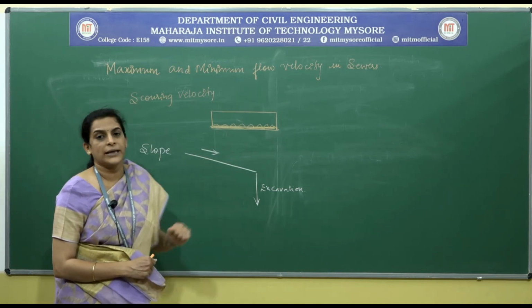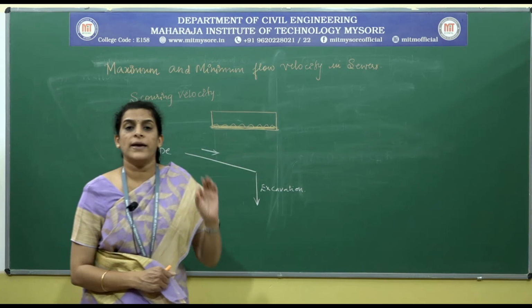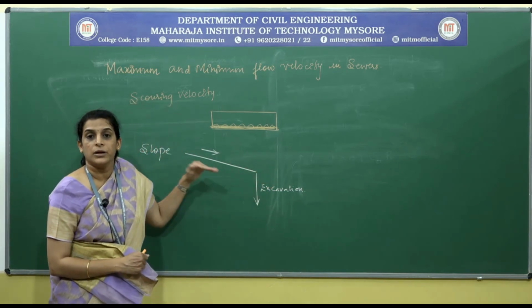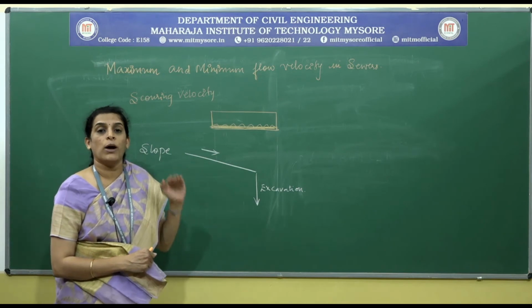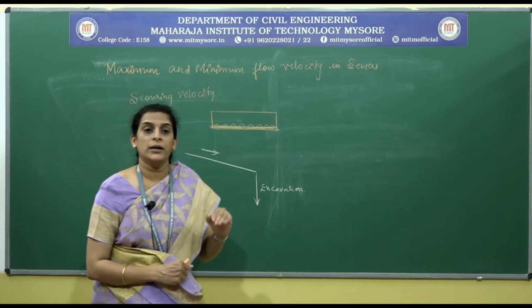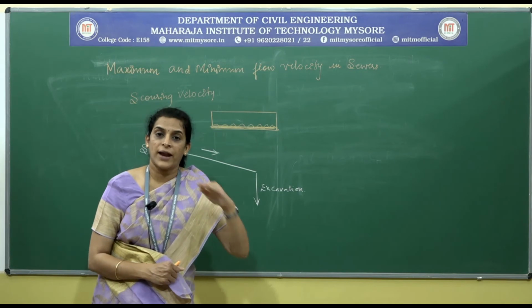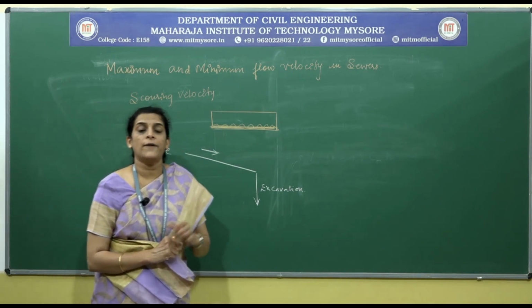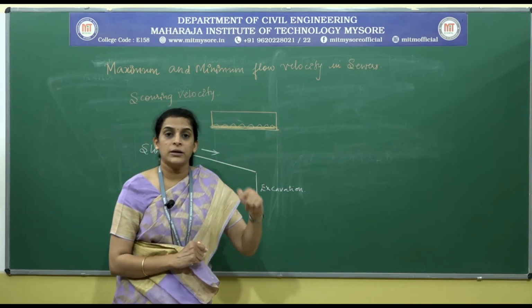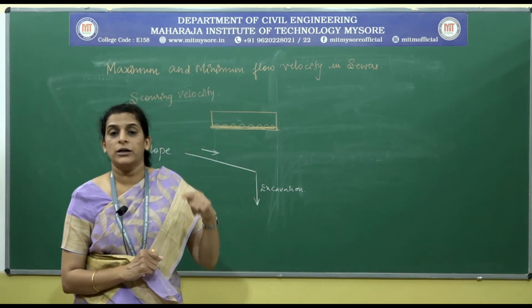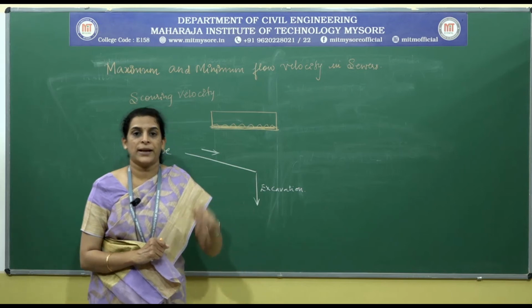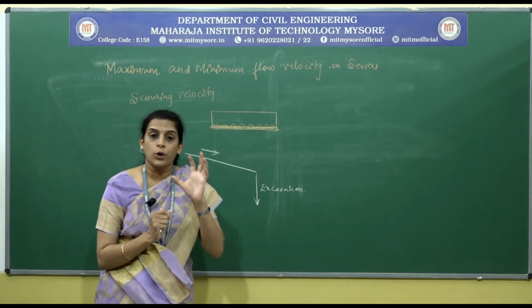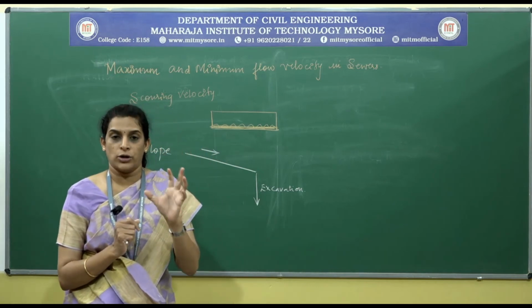But one thing I can tell, not always will we have a suitable gradient. Of course, we will have to work in conditions wherein there will be a mere flat surface also. In those instances, we will have to go for steeper slopes. In turn, we will have to go with deeper excavations, so as to make provision for proper achievement of velocity.